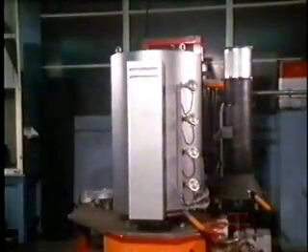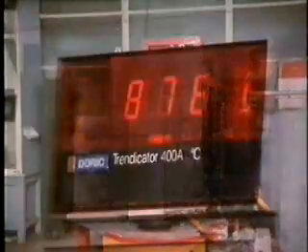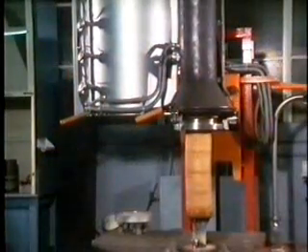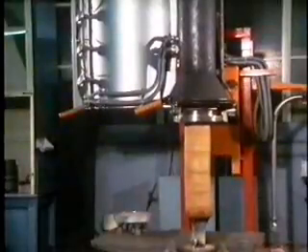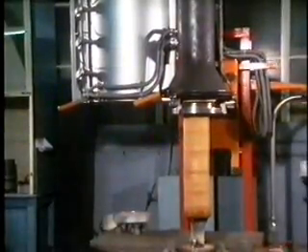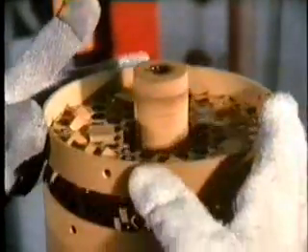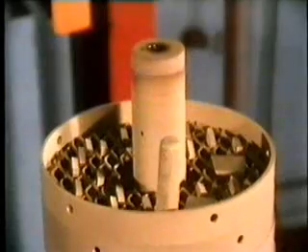After checking the final geometry, the insert undergoes facial and peripheral grinding. Although the inserts can be used at this stage, most undergo a coating process. Placed for about 9 hours in a vacuum chamber at temperatures exceeding 1,000 degrees centigrade, a very thin coat of titanium nitride or carbide, about 6 or 7 microns, is added to the surface. This coating improves the cutting properties of the material and extends the life of the tool.